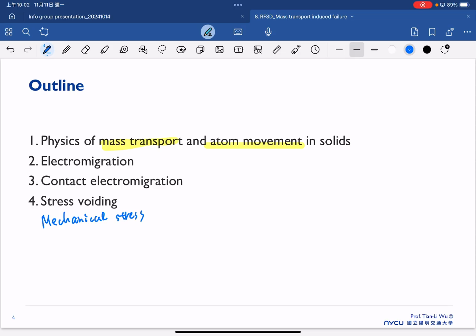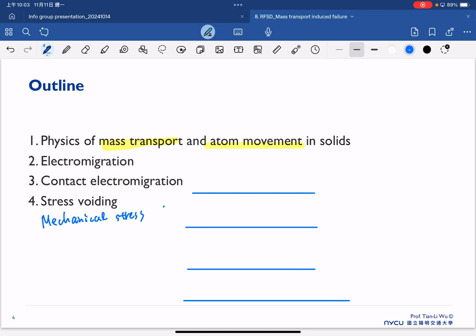So in the back end of line, we actually have lots of metal and lots of passivation. Imagine you have the metal 1, and you have the metal 2 here. So that's our M1 and M2. And of course, to isolate the signal between metal 1 and metal 2, we definitely need to deposit a certain insulating material. That's what we call the passivation.